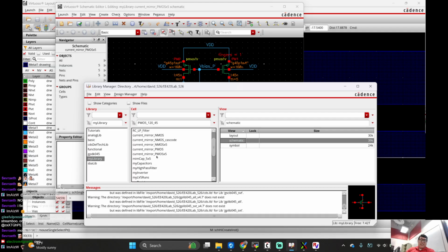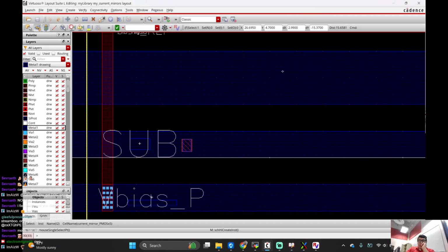So what I'm trying to say is, current mirrors, usually you have an NMOS tied with a PMOS, okay? PMOSs can't exist without something pulling them down. There's no reference. So you want to know how I would have fixed that problem altogether? Instead of making you do a PMOS current mirror separately and an NMOS current mirror separately, you put them all together as one big PMOS NMOS. That would have avoided the whole situation entirely. I just put a tap in there.